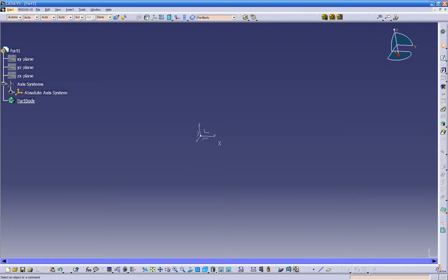Let's go back again to the sketcher. Let's play more with the sketcher and learn a couple more things, how to build some rectangles. So let's go back to the sketcher. Once you click on the sketcher, it's going to ask us to select the plane, or the planar face, or the sketch.